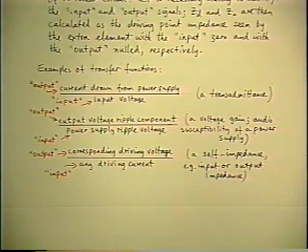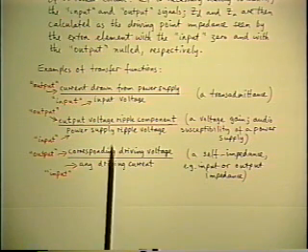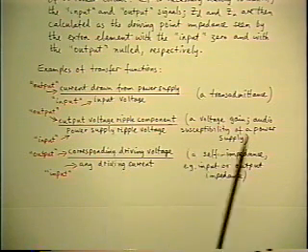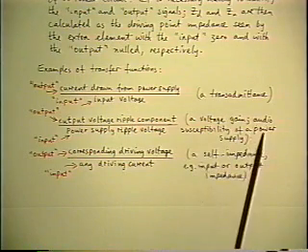Exactly the same sort of transfer function also applies to a regulated power supply itself. That's actually an amplifier as well. And it takes an unregulated rectified line, maybe with a lot of ripple on it, and there is also a specification on the power supply that says its regulated output voltage has to have less than so much ripple in it. So that's another voltage transfer function, which is often called audio susceptibility.